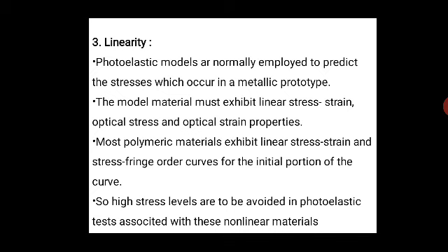Since the model to prototype scaling must be used to establish prototype stresses, the model material must exhibit a linear stress-strain relationship, and optical stress and optical strain properties should also be exhibited in the linearity.